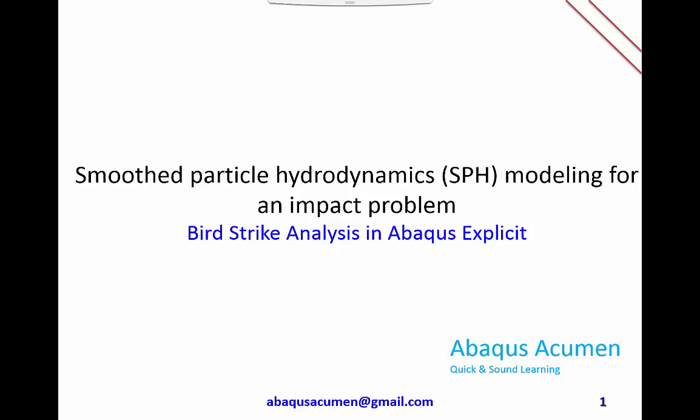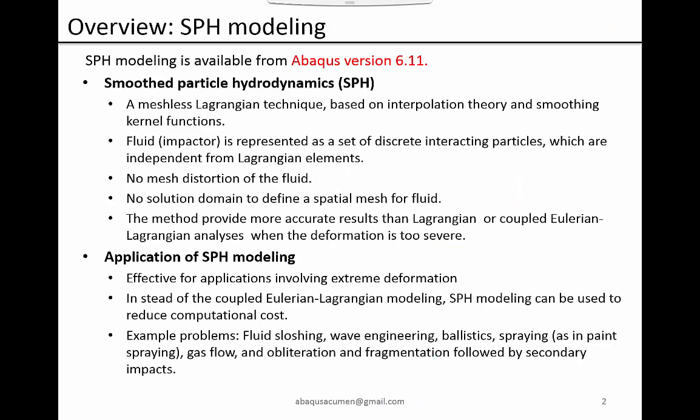Smooth particle hydrodynamics modeling for an impact problem. This is what exactly we are going to do. We are going to do a bird strike analysis in Abaqus Explicit. Just a quick overview on the SPH modeling. SPH modeling is available from Abaqus version 6.11.